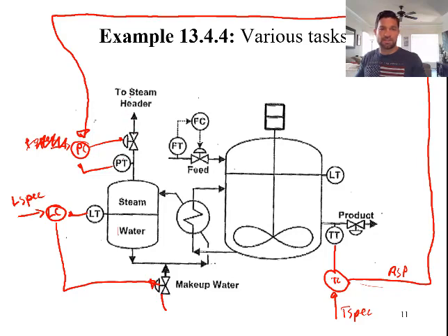And so it's going to either release more pressure, release steam, or hold the steam. As we release the steam, the level in the tank is going to change, which is going to bring water into the system, which is going to have a cooling effect. If we don't release the steam, we're not going to bring water into the system, and the temperature is going to continue to increase. So these two loops are related to each other, but they're still separate in terms of how they work.